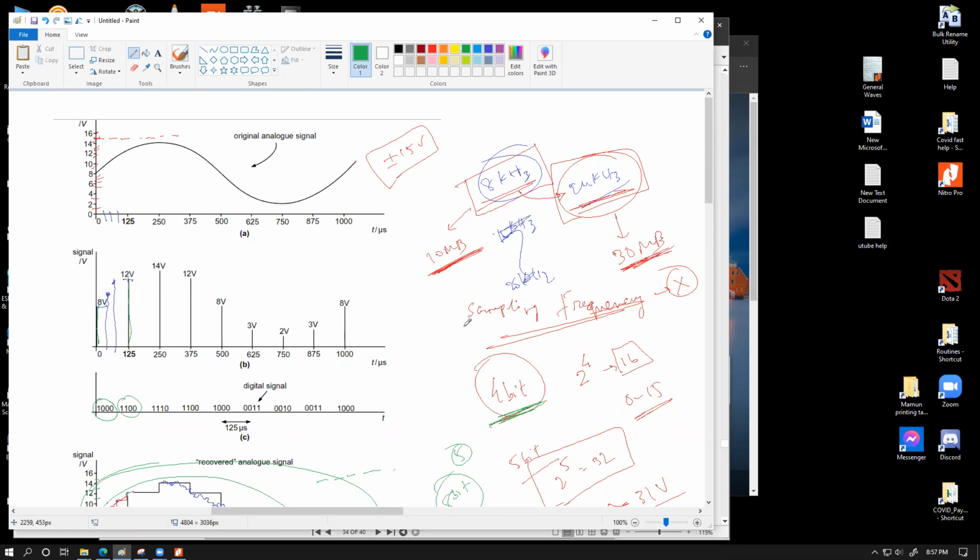But if you're in the audio business, having high quality data essentially gives you more data. And this also brings us to another interesting point, which might be a part of your discussion in your question: can we make a small file into a larger file just by incrementing the data? For example, if a certain audio file was 8-bit and, let's say, 100 kilohertz sampling frequency, without having the original analog signal, can you simply make it 16-bit and 200 kilohertz? The answer is yes, you can, but that would not increase the quality of the whole thing. That will simply make the file size bigger. You'll basically be looking at the same thing twice.